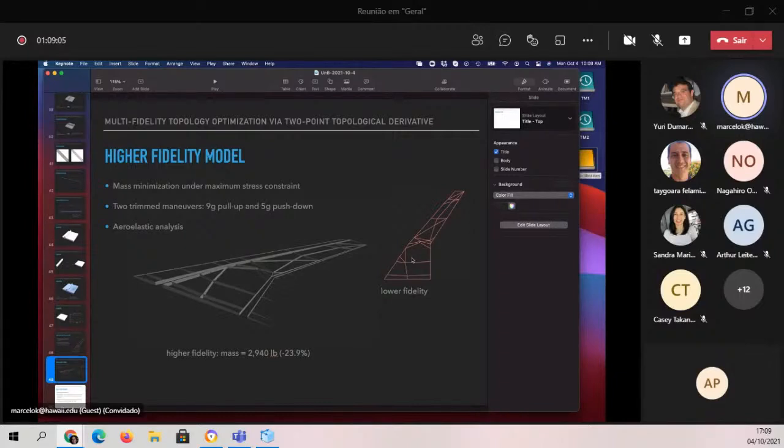I use Gmsh, and Gmsh is a nice tool, because the challenge many times is to automate all of that, but you have this available in Gmsh, where you can tell it you have special points where you want to refine the mesh more around them and things like that, right? And so I can do a remesh, but doing a remesh can be very expensive, as you mentioned, right?